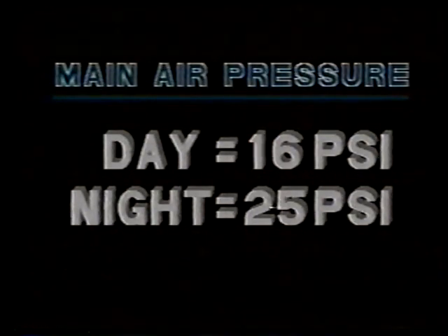temperature. For example, a school may want its classrooms to be 72 degrees during the day because of classes, but at night, when the classrooms are unoccupied, they need only 60-degree space temperature. Changing the main air pressure to the day-night thermostats in the classrooms will allow them to set back or set up the temperature in the classrooms during the unoccupied hours.